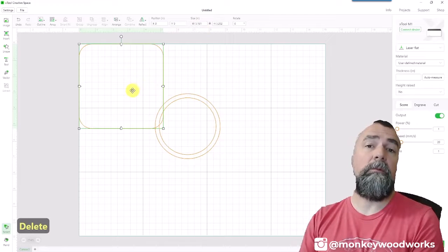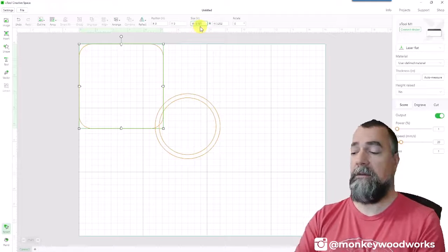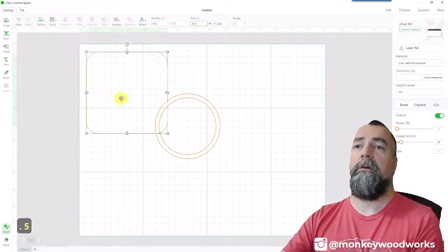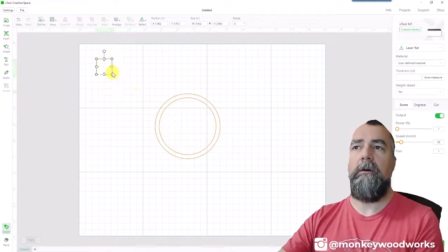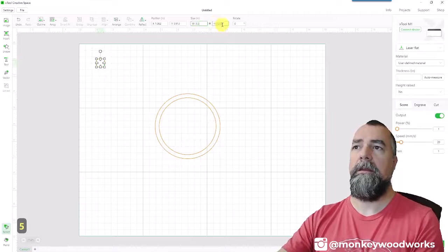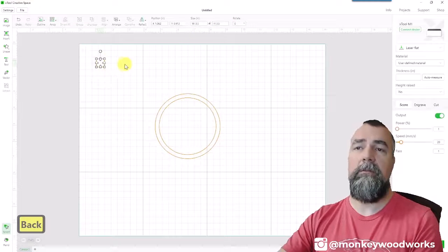Now the problem with XCS, there is a bug in there where you cannot come up here at the top and change the size by typing 0.5. The point doesn't show up. So unfortunately, what you have to do is kind of drag this to get below that into the decimals. Then I can actually modify it and put 5, right? And this is off, so let me change this, unlock it so I can adjust them individually, take that out, and now it's 0.5 by 0.5.